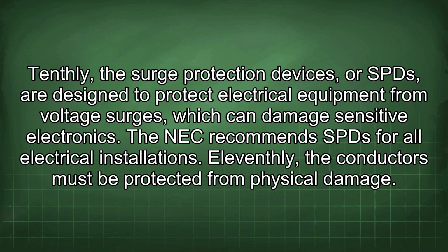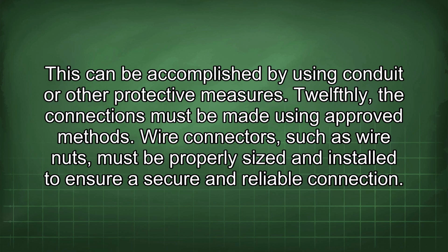Tenthly, the surge protection devices, or SPDs, are designed to protect electrical equipment from voltage surges, which can damage sensitive electronics. The NEC recommends SPDs for all electrical installations. 11thly, the conductors must be protected from physical damage. This can be accomplished by using conduit or other protective measures.